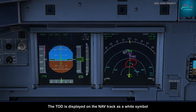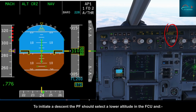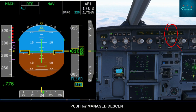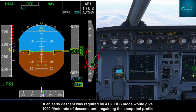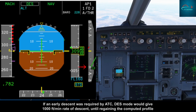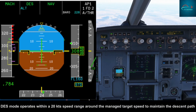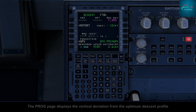The top of descent is displayed on the nav track as a white symbol. To initiate a descent, the pilot flying should select a lower altitude in the FCU and push for managed descent. If an early descent was required by air traffic control, descent mode would give 1,000 feet per minute rate of descent until regaining the computed profile. Descent mode operates within a 20 knot speed range around the managed target speed to maintain the descent path. The progress page displays the vertical deviation from the optimum descent profile.